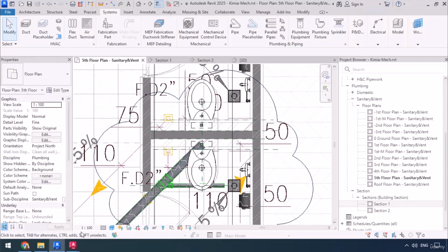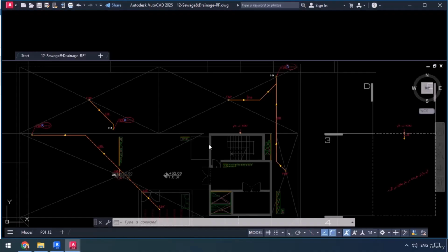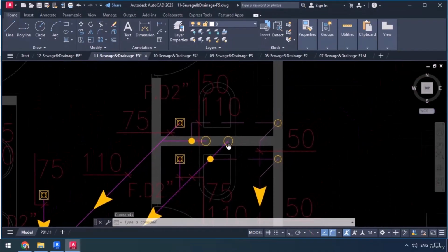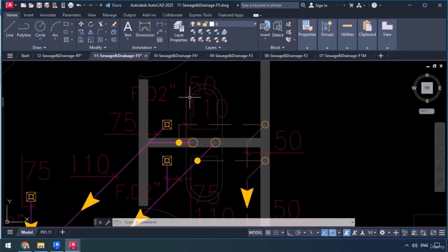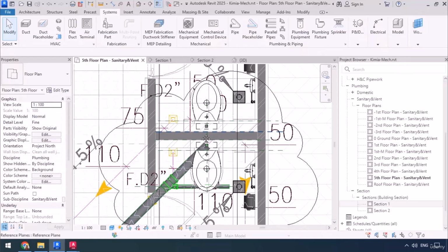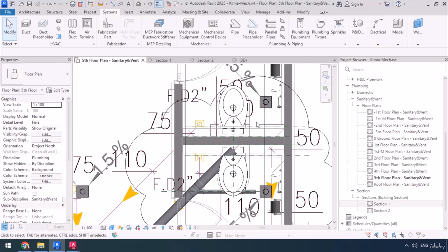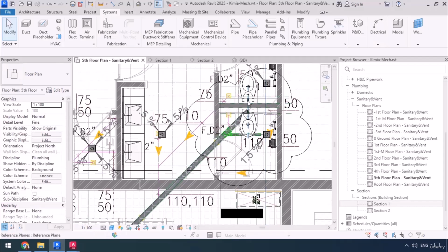Now also, because the fixtures are placed in the architectural model, we could place this pipe approximately adaptive to the fixture's locations. Now if we could take a look at the CAD plan, let's go to the 5th floor. Here we are, we can see that even clearer. So you see the sanitary pipe, which is for this toilet over here, is coming through this wall, then leads to the left with the floor drain pipe connecting to it, which we're just going to have to model differently, as in we're going to have to draw the pipe this way, but the floor drain was placed at a different location. After that, according to the CAD plan, the pipe came in here, it was drawn this way and eventually connecting to the main pipe.